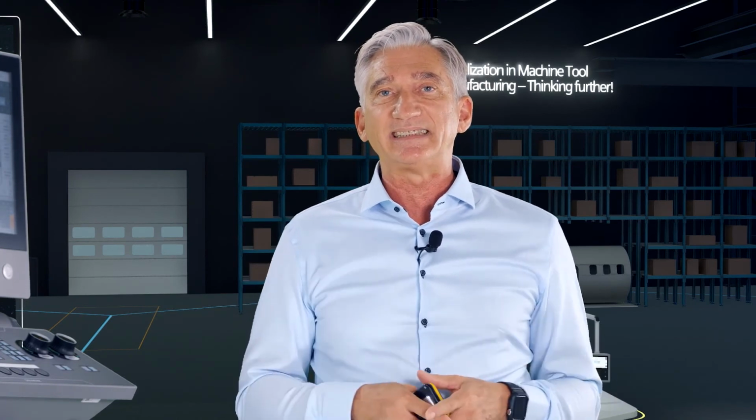Thank you. I would like to come to the typical job shopper. If this job shopper gets an order from his customer, the question arises, how does he turn this order into a CNC program as fast and efficiently as possible? A possibility which is available for a while is the DXF reader option, if the workpiece description is available as a DXF file. In that case, the machining elements can be extracted only in 2 dimensions.